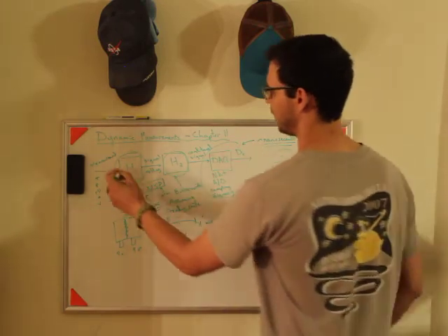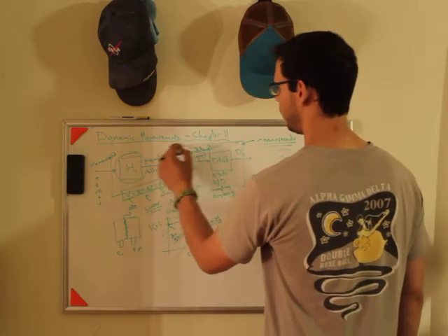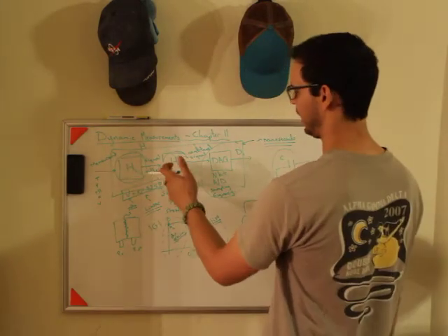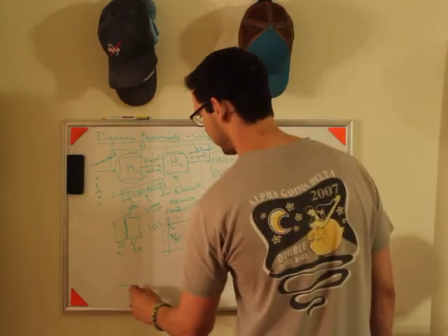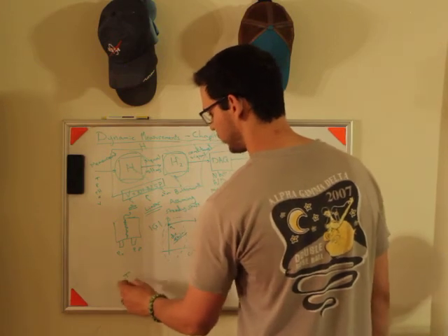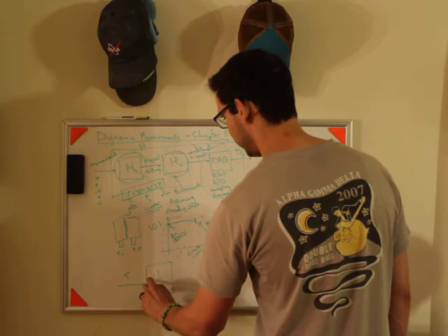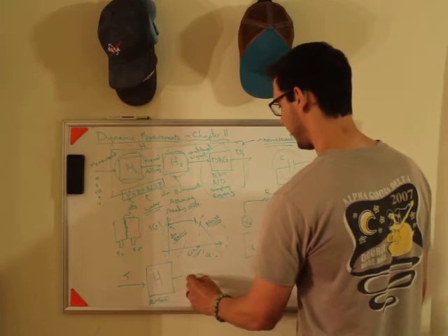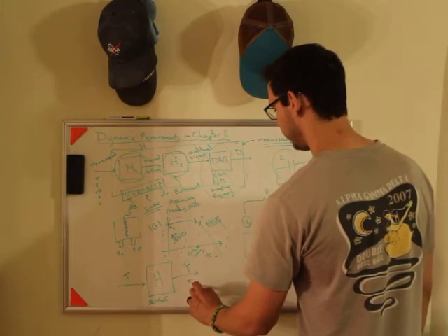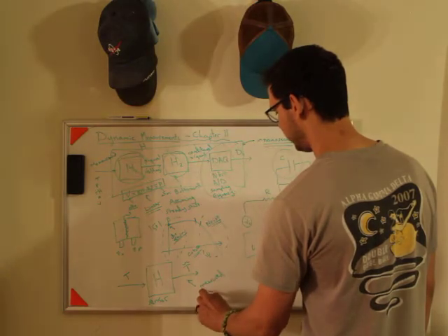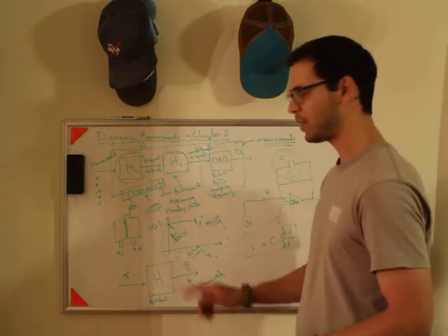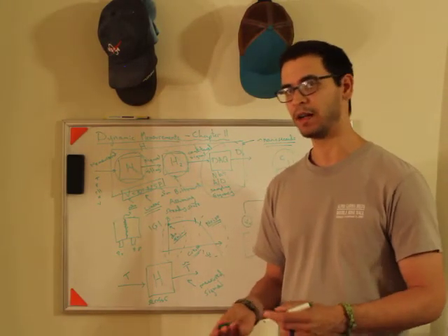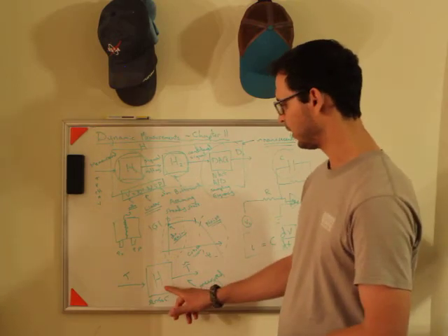And if you put this all together, and you just make this one huge loop, and call this H, just capital H, so this is like H1, H2, and that's like H3, you can assume that your input, I'm going to say temperature in this case, is T, and my sensor block is H. My output, I'm going to call T tilde, which is my measured signal. And that measured signal is going to have noise, delay, scale factor, bias, cross sensitivities, all of the different things, and they're all going to be embedded in this.